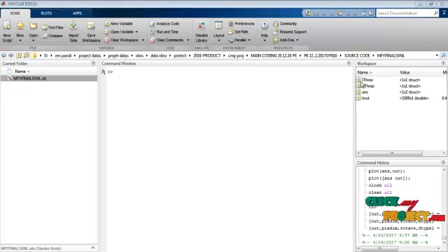Next we see about the running process of our product. The proposed implementation is done in a MATLAB simulating environment. First open the MATLAB main window and create a new model file. After creating a new model file, we arrange the elements from the library browser in MATLAB. From the library browser we mainly used two blocks. One is the SimPowerSystems block, another one is the commonly used blocks.